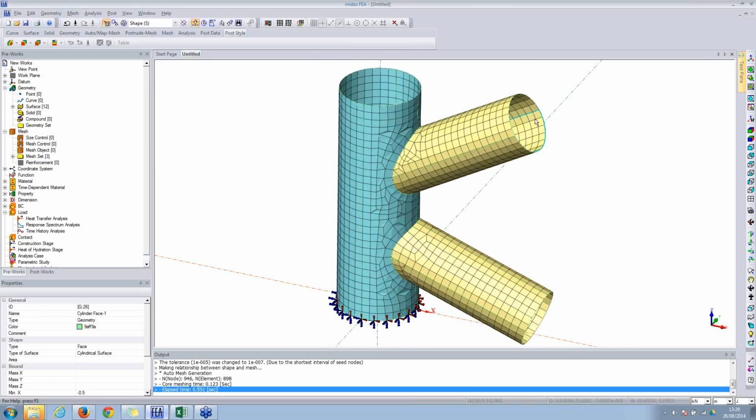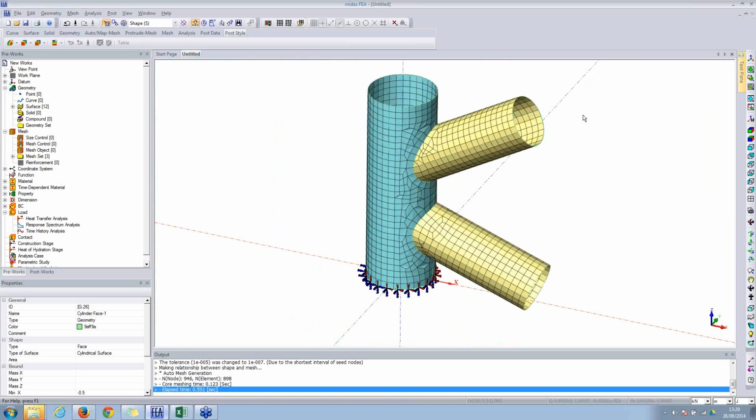Now what happens is when we do this type of analysis, we normally have the loads as point loads, which we calculate from a simple frame analysis. From a simple frame analysis, we may get some axial forces in the bracings and in the columns, some bending moments. So some forces we get, but these are just point concentrated forces, acting along the centroid.